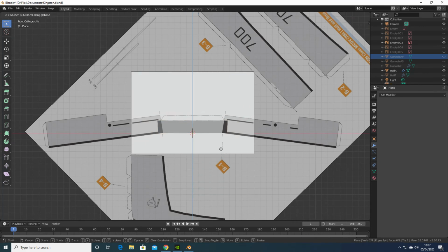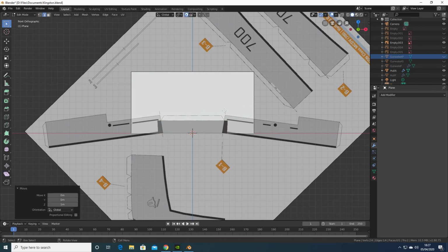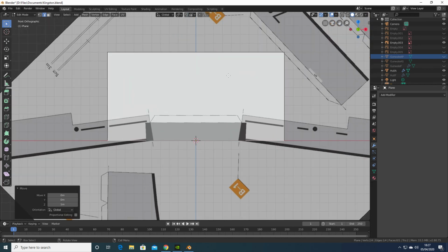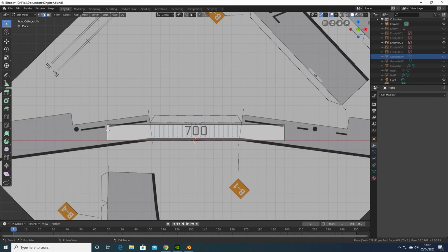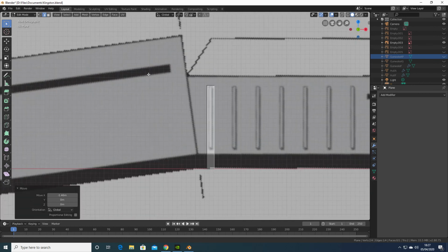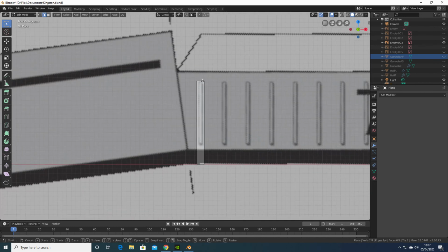We'll take this first edge and we'll snap it to the base here. We'll hide the aft hull. We'll select this one and we'll GZ and bring it down to the level of the top of the strakes. We'll take this and GX and just pull it into this first one. Take this edge and GX and pull it in so that it's roughly aligned with the reference image. Now we'll just fine tune, so GZ and GX, and just using the shift keys just to fine tune it.